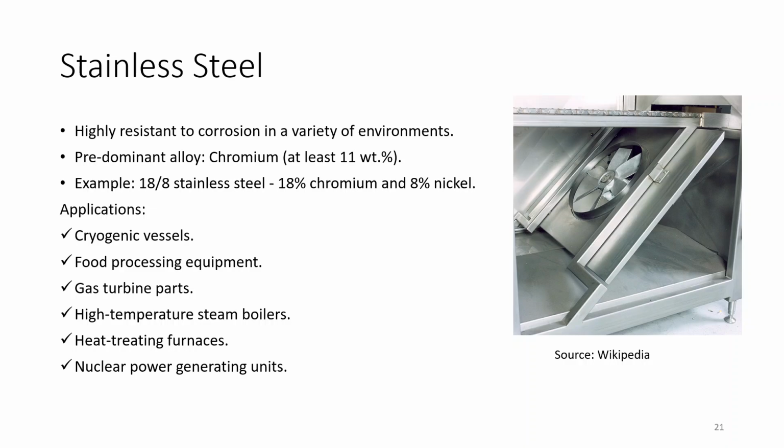Okay, so at the temperature at which you are melting your steel, steel is mainly made using a recycling type of process. You take scrap and melt it, and then you add elements to reduce the oxygen percent. Here you already have a carbon percent, so you don't add carbon intentionally. In other processes, you use pig iron as the raw material for steel forming.